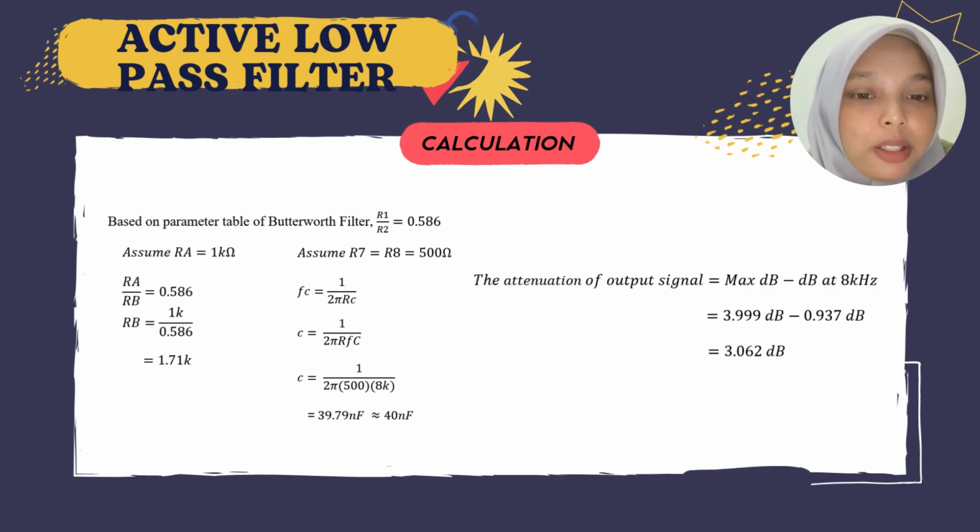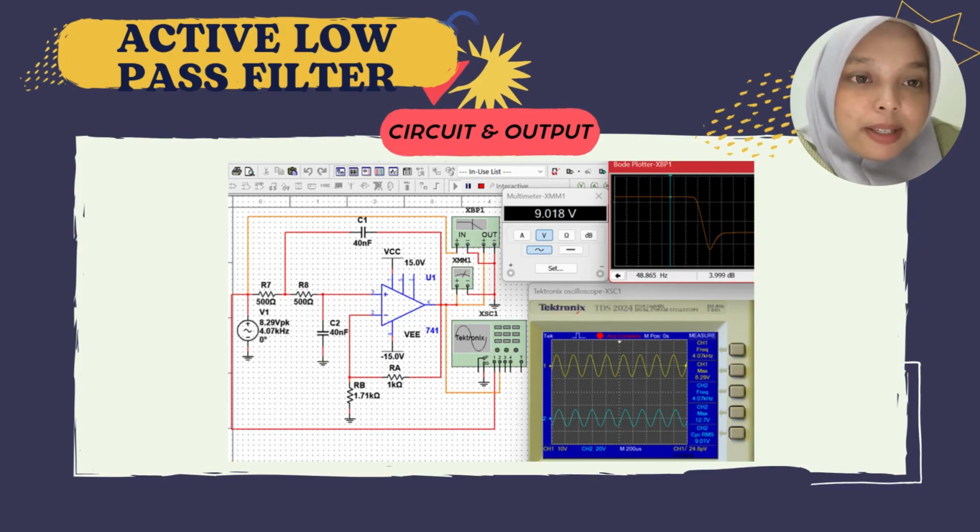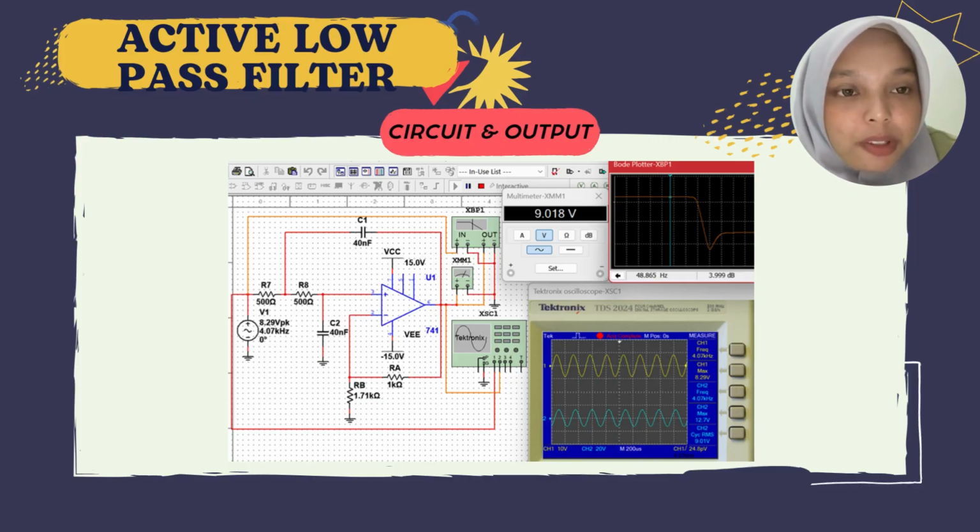Last one, the attenuation of the output signal. The formula is max dB minus dB at 8 kHz. So the max is 3.99 dB minus 0.937 dB. So we got the final answer of 3.062 dB. This is the result and output for the active low pass filter.